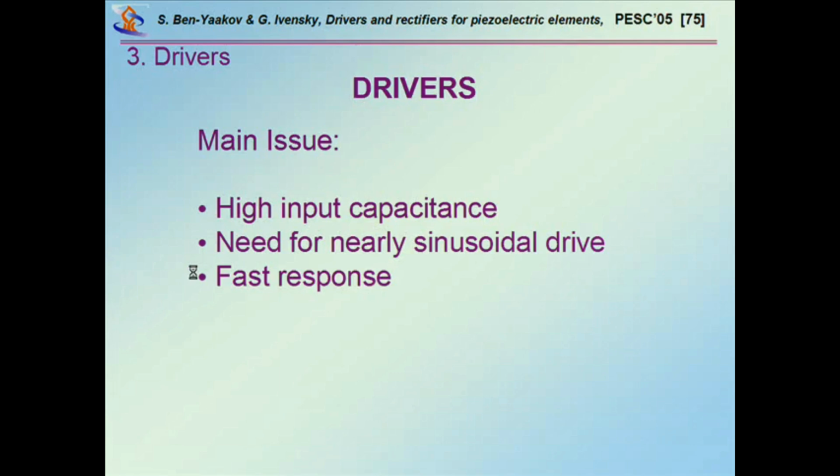Now I'm going into the area of drivers. That is, how do we drive piezoelectric elements? And again, we'll go over the various elements and see what solutions people are using for these drivers. Now, the main issue that we have is the high input capacitance. That's a real problem, because the reactive current is very large, and therefore the circulating current is large, and if you want high efficiency, you have to do something about it.